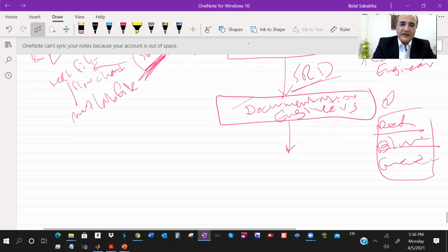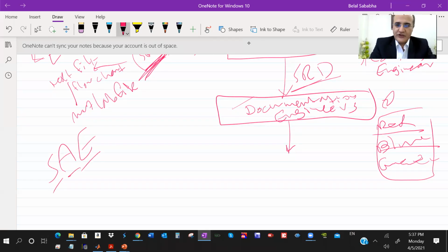And guess what? There are standards in the automotive industry. There is an association called SAE, the Society of Automotive Engineers. This is like IEEE, but for automotive engineers. They have requirements on how a software requirements document in MATLAB should look. What is the color of the line connecting two blocks? What should the block color be if it is a RAM variable, a constant, or stored in EEPROM, a calibratable? They go to that level.